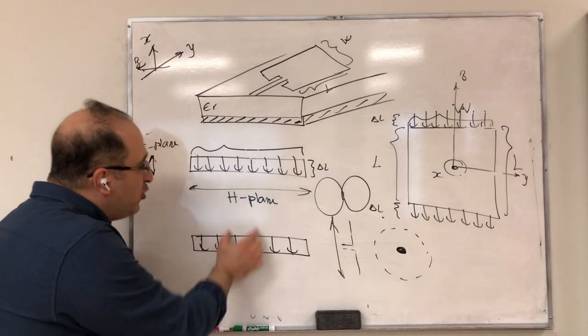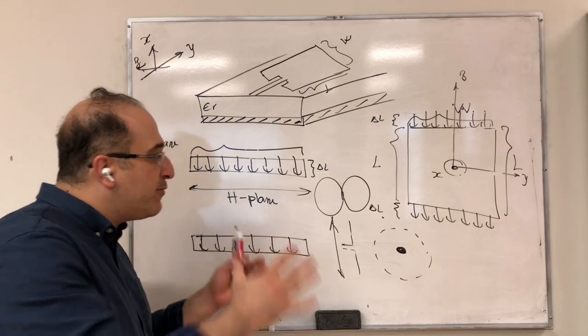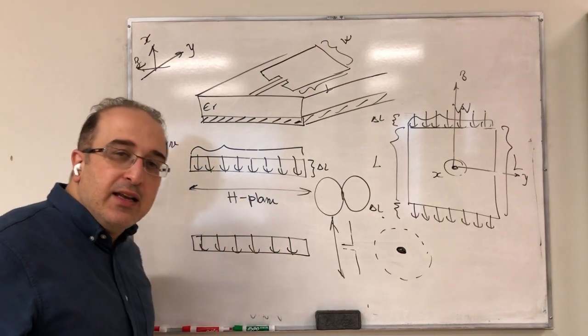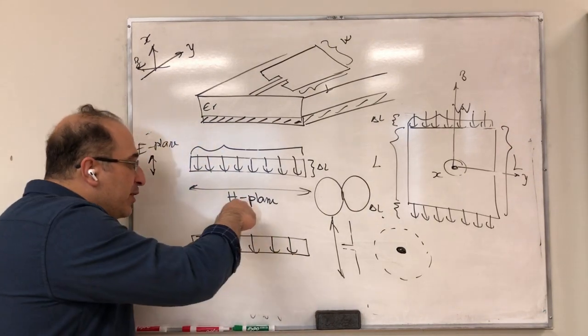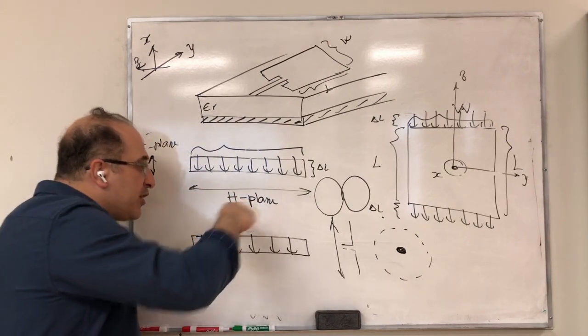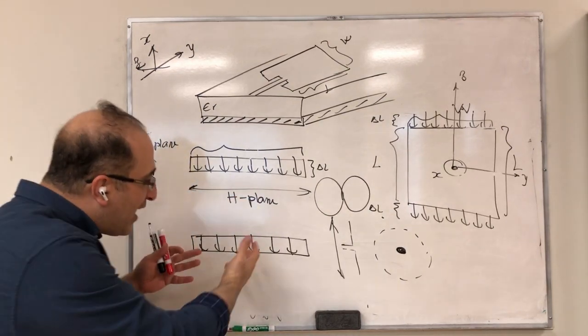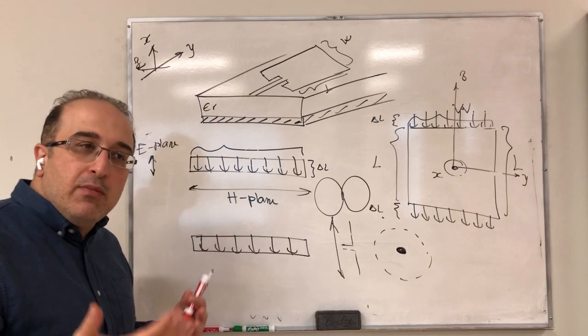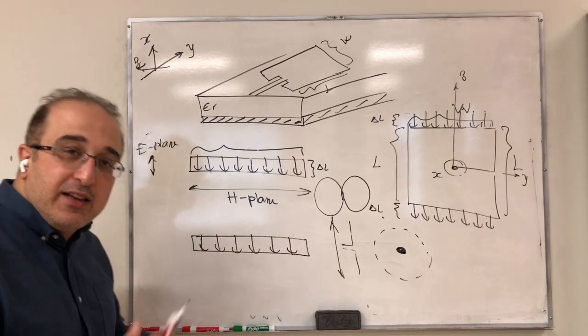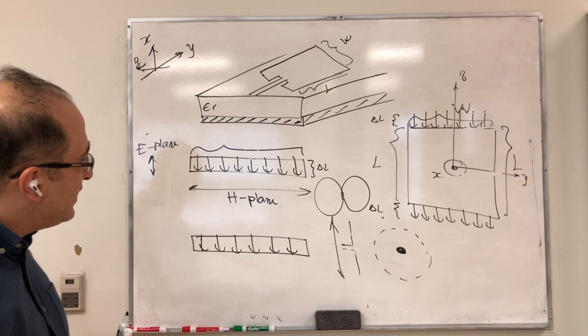For example, you design this electric field to be in phase, so they have certain characteristics. For example, the main beam is essentially perpendicular to the patch, but you could also have an electric field with some other distribution, and then you can change the way that it radiates for you.